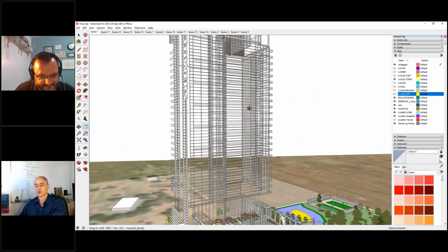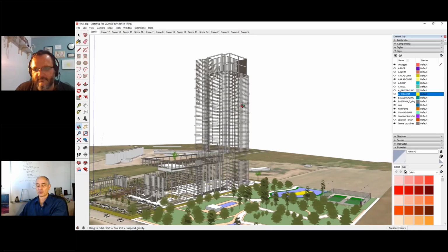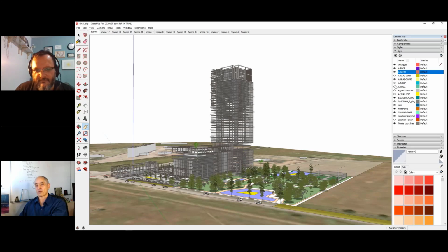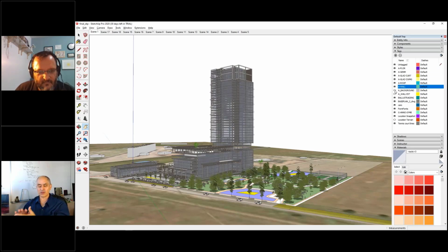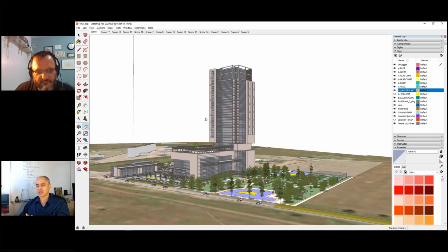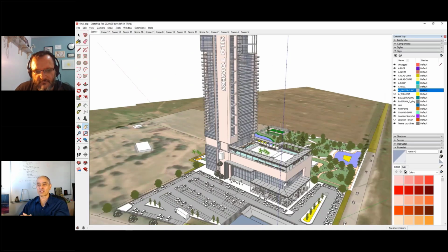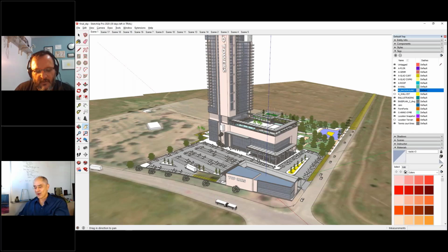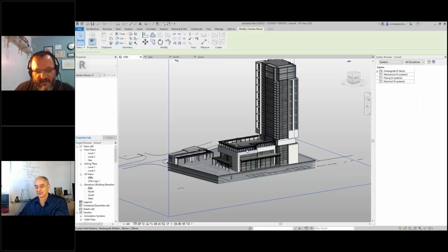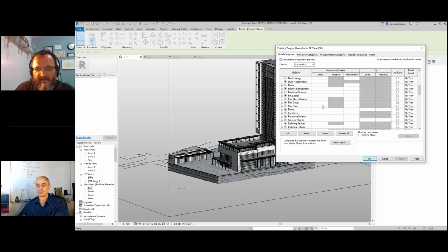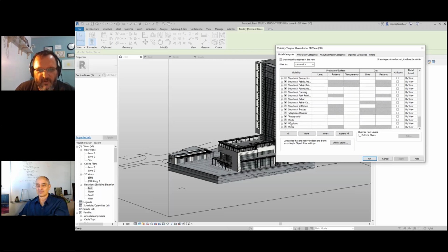So interesting. They resisted layers for forever, and I remember when Revit first came out, one of their claims was, you don't have to worry about managing layers. You know, we sort of show the right thing at the right time, etc. But when you export it, it's creating the equivalent of layers, and in this case, it's called tags in SketchUp. Okay. No, Revit does have layers. If you go into the VV menu here, except the way they sort their layers out is like, if it's walls, it will be called walls over here. They're called categories, model categories.